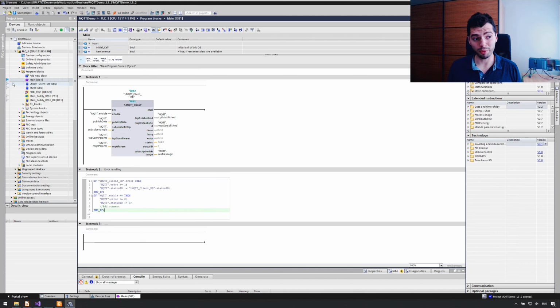in main. Immediately it's going to get a blue flag. This means it's marked for check-in. All the objects marked for check-in will be sent to the central project when you check in. So that's like a good flag. That's a normal flag. Blue flag is okay. It just means that you made some changes to this. It's no longer at the same stage as it is on the central project server. And when you do the check-in, it's gonna send them.